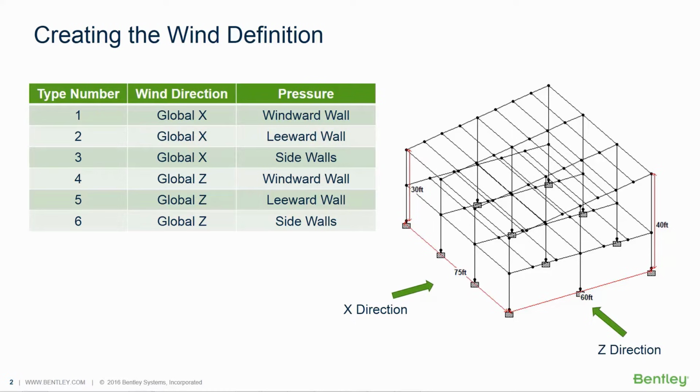As wind loads are developed for a structure, it is not uncommon to find the values for these parameters may vary depending upon the particular direction of wind being considered. This points out that certain amounts of prior planning can be helpful when establishing our wind loads. For our sample model in this course, it will be necessary to define the wind loads in the X and Z directions separately, since the building dimensions are different for each direction.